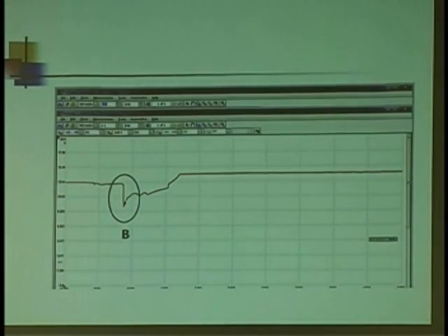The same way, looking at the inrush voltage, what I still call loaded voltage, if you get a number of about 8.5 or better, the battery's in pretty good shape. If you want to double check and use the old way, then you just go back to the pattern where your current intersected that 200 amp and see where it intersects with your voltage. That will be the 9.6 or better that we're used to. Okay.